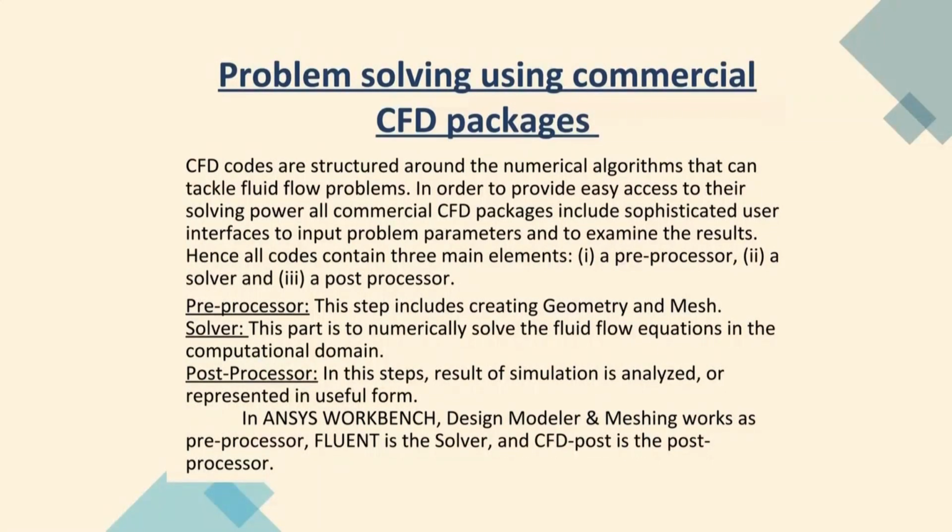It is solving and storing data at all the nodal points. Professor already mentioned the nodes. But if you want the result somewhere else, in between nodes, you need interpolation. That is what the post processing software can do for you. And Ansys Fluent, or Ansys, has its own CFD post.